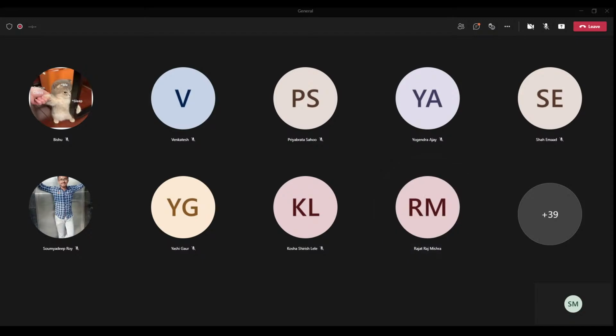Hello. I wanted to ask, can I use a DC adapter? I currently don't have a battery. It's rated 9 volt and 800 milliampere. You can use a DC adapter, but just see the rating. It should be around 12 volts. Yeah, it is written 4 to 12 volts and 800 milliampere. Yeah, it will work.